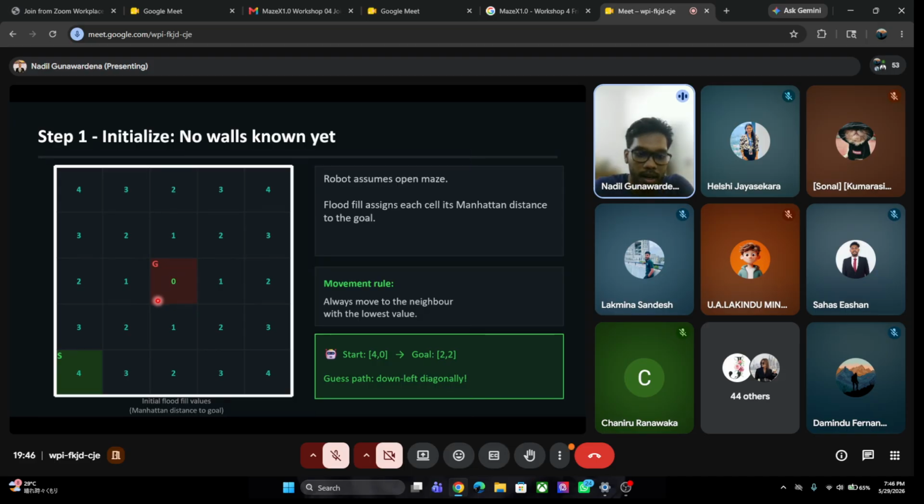That means you can hard code it, like we have also built micromouses. What we have done is, if you receive 2 or 3 possible paths, give priority to the right path, front path or left path. We just set a priority, and according to the priority we have set, it moves.